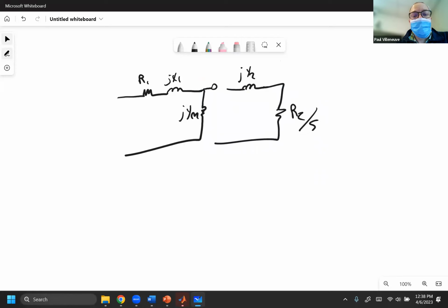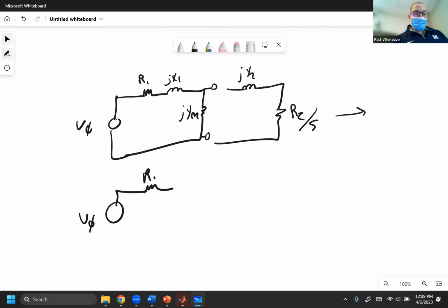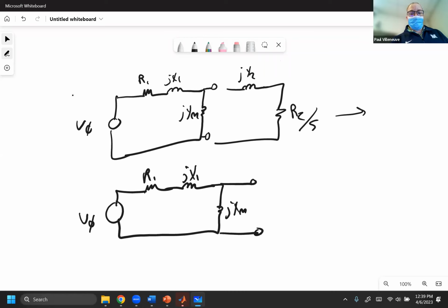But the whole thing about the Thevenin equivalent is I open circuit the terminals of what I'm looking for, and then I solve for the Thevenin equivalent. So as I said, this gets moved off to the side. So the only elements of the circuit that I see are these. And since I'm looking at this terminal point, I'm looking for V Thevenin and Z Thevenin.